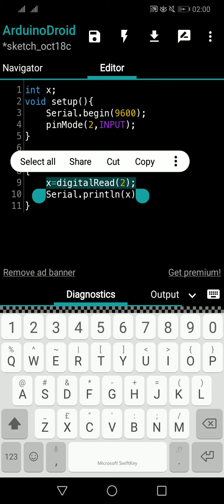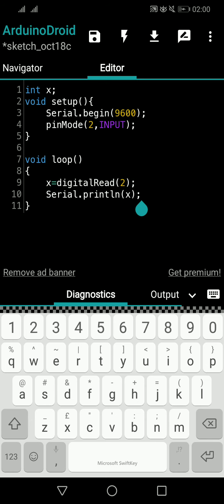What will happen in the pull down circuit? The other way around, right? If you don't press the switch, it will be 0. If you press the switch, it will become 1. You understand what I'm talking about? If you don't, go watch the previous video and come back. I don't want to waste much time on this video, because it is almost the same as the previous one, only the terminals are different.